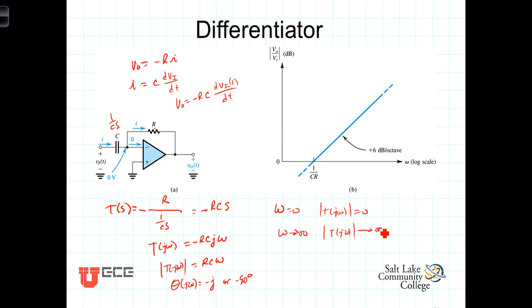From a practical perspective, differentiation accentuates changes in the signal. If the signal is tainted with noise, the differentiator circuit amplifies the noise and limits its usefulness in many applications. Under those circumstances, where you do actually want to use it, they will typically place a relatively small resistor in series with a capacitor to limit the current spikes resulting from the differentiation of the noise.